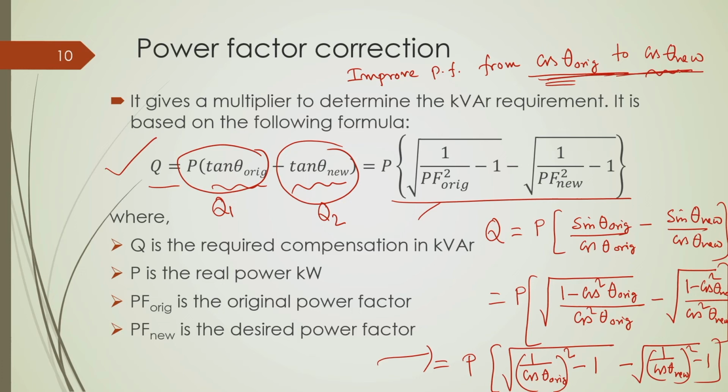Otherwise, you can do a step by step analysis to find out what will be the active power demand of the source and what should be the reactive power demand after placement of the capacitor, and step by step analysis will provide you the result. Then you do not need to keep this particular formula in memory.